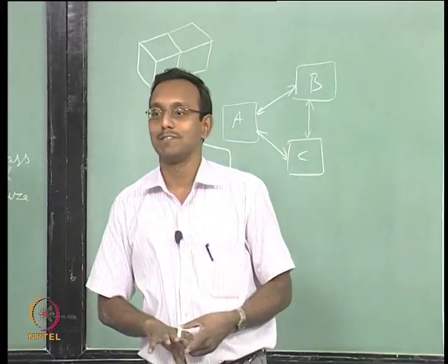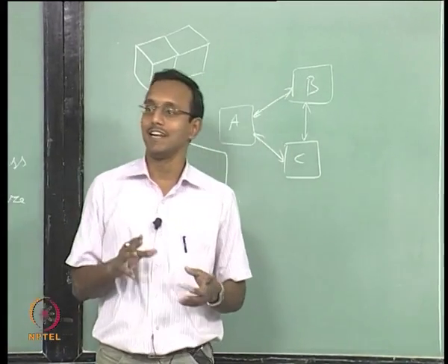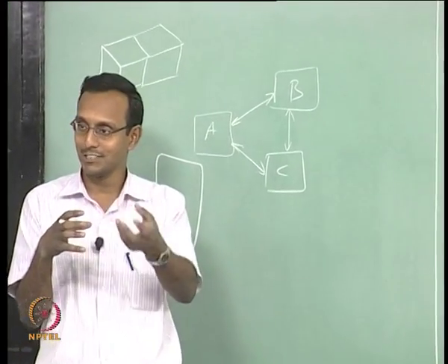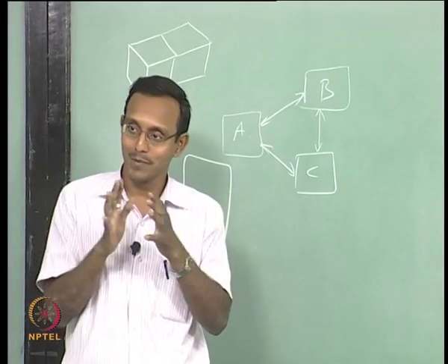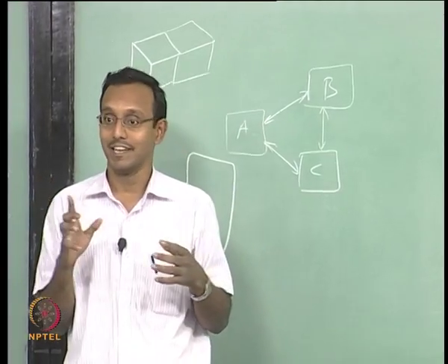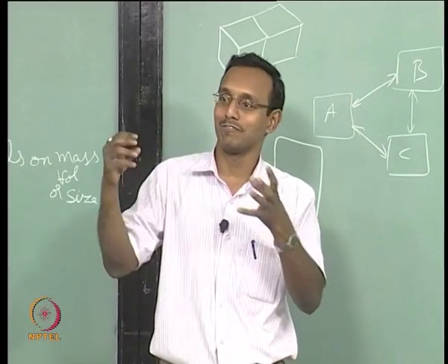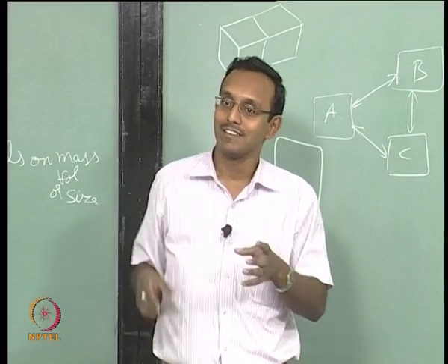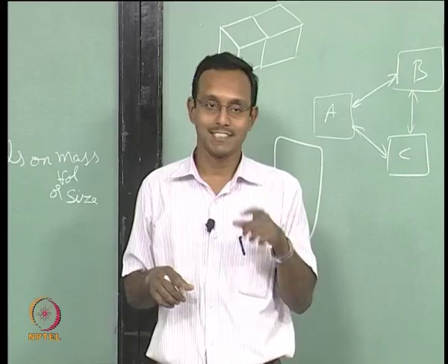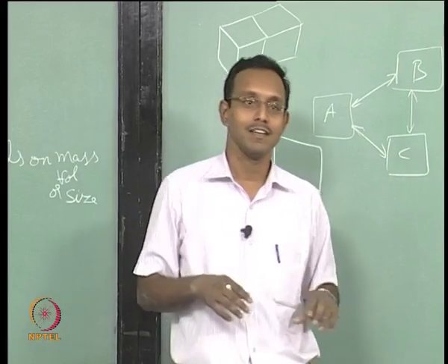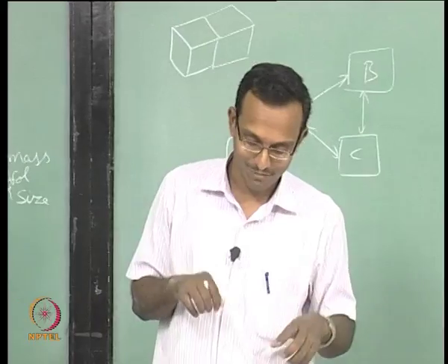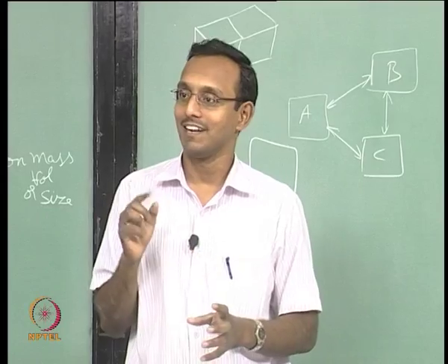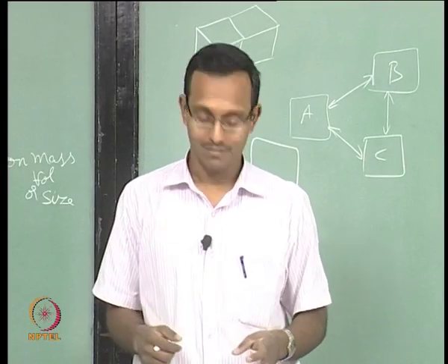Of course, in a simple compressible substance, the only kind of energy exchange with my system happens to be through heat exchange or through compression or expansion work, nothing else. We will not consider the case like I put a fan inside my system and rotate it, that is stirring of my gas, which we are ignoring as a simple compressible substance. We will not have stirring case. If I stir a gas for a long time, its temperature will increase, but we will neglect that kind of energy transfer.